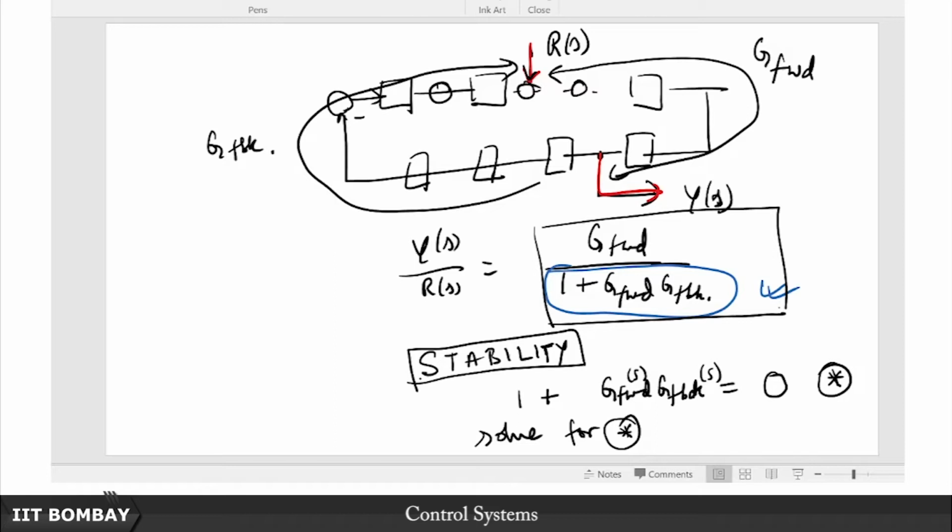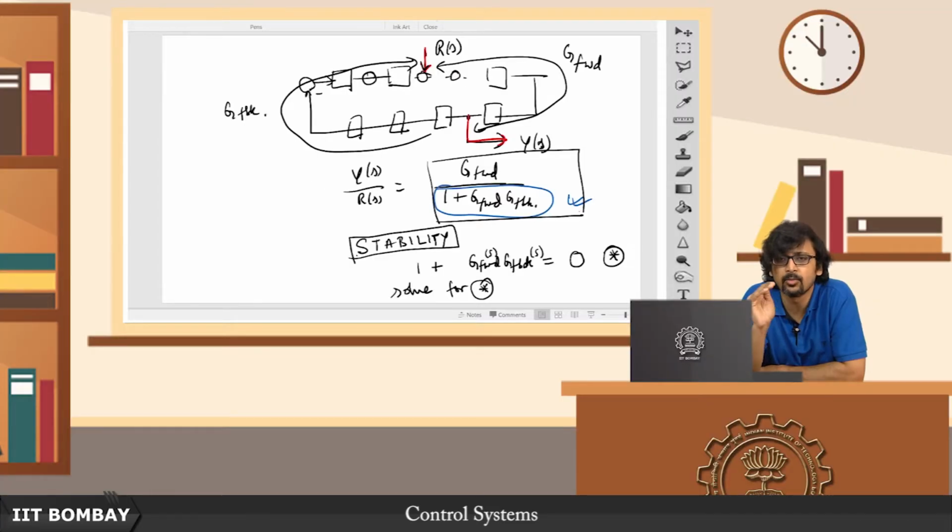We will be studying the steady state behavior, the errors arising in a system that is put in a closed loop configuration. What sort of errors? So we will take this reference signal as our input, and we will track the output, monitor the output, and take the difference between the two, which is basically the variable that drives the system. This is basically r minus y, and that is why we are in love with this unity feedback loop, because there that r minus y is clearly seen to drive the system. So this r minus y, we want it to go down to 0. In other words, we want the output to perfectly track the reference input.